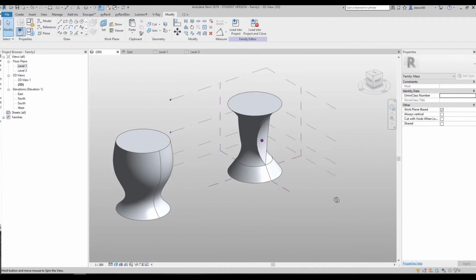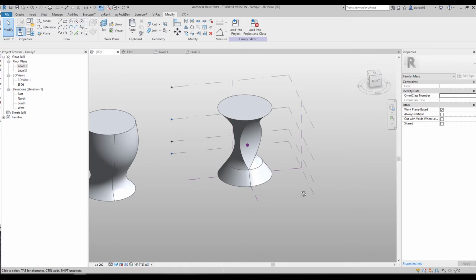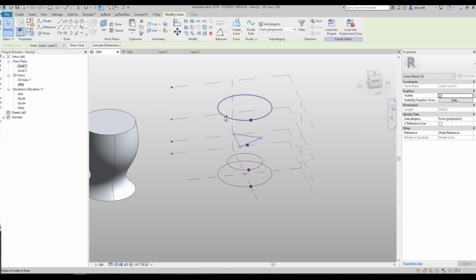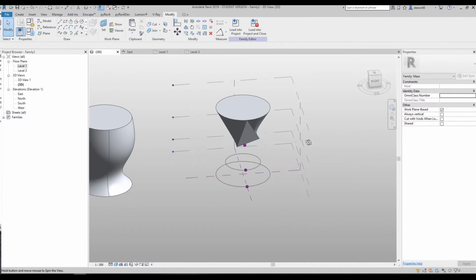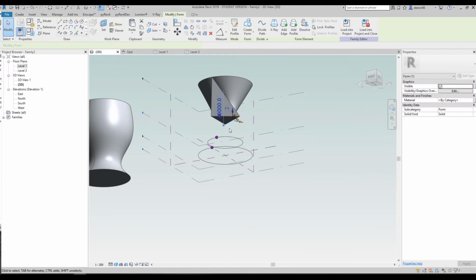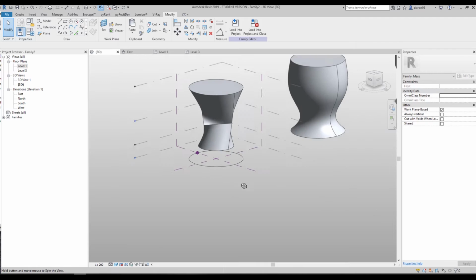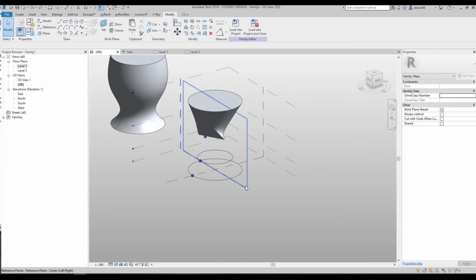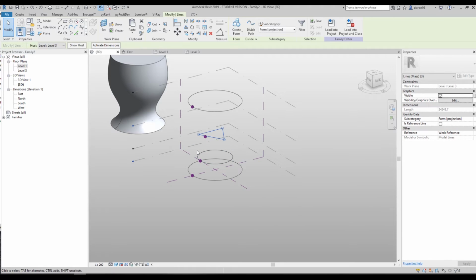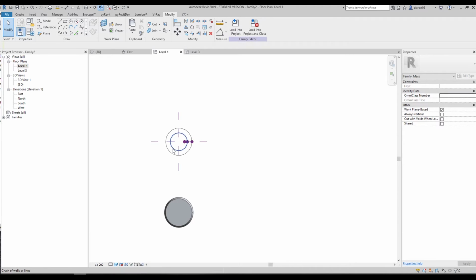Of course, Revit is trying to do that. Revit is not perfect with working with splines. As you can see, it's not perfect at all. But we have one thing. If we create again one by one, we will get a bit different type of connection, as you can see. For example, let's do it one more time. Select the triangle here. As you can see, we get a bit different type of connection. Of course, you should be careful when you create your shapes, because not all shapes can make nice connections between each other. What I want to say to you.